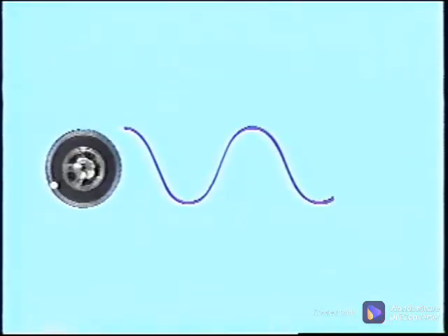In a previous program, Introduction to Vibration Analysis, we used an unbalanced tire to show how a waveform is simply a trace of a machine's movement over time. Notice that as the wheel turns 90 degrees, the trace also moves relative to the center line. A 90-degree rotation in the tire from the top corresponds to a movement in the trace from the top to the center line.